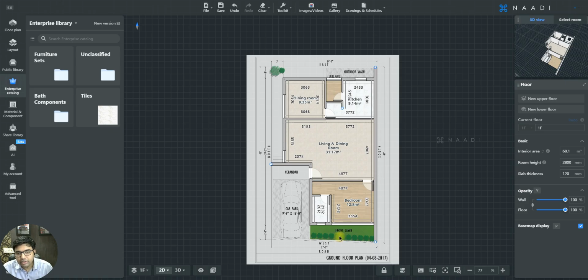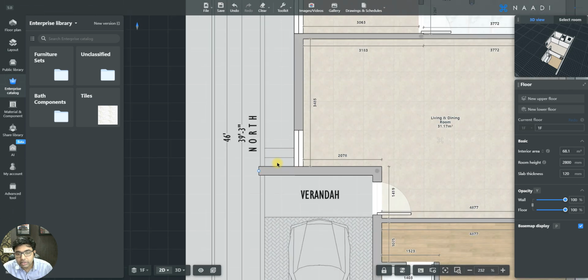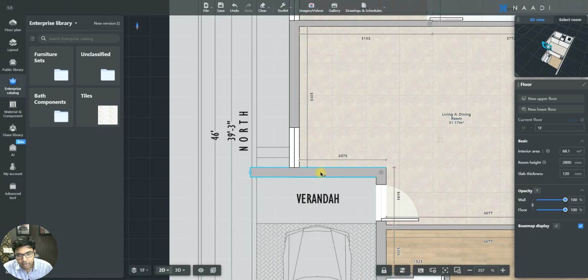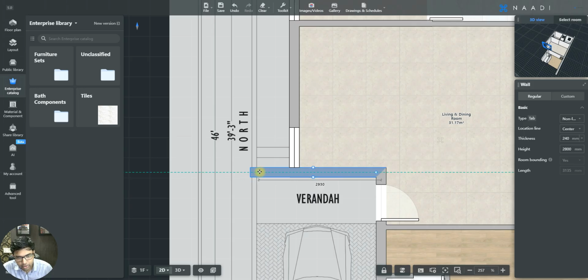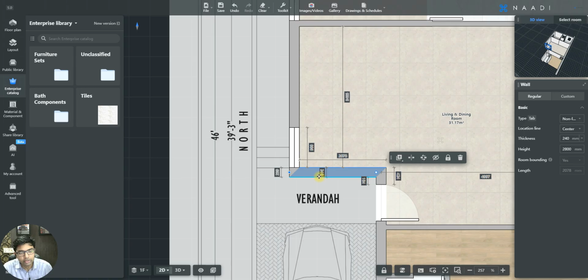The second inspection is if some walls extend beyond their length, you can adjust the length. A best example is this one here. Here can you see this wall is extended till the setback region. So this shouldn't be. I can just drag it and get it back to the position. While you are setting it back, just place it at the corner. That's it. It will auto snap to the point and it will create a seamless corner here.